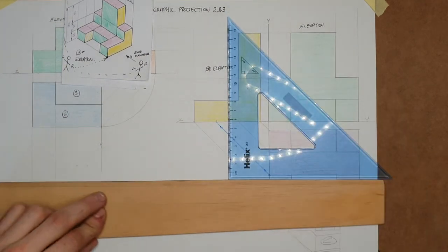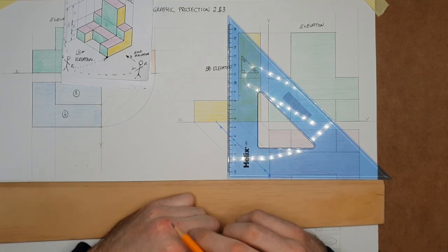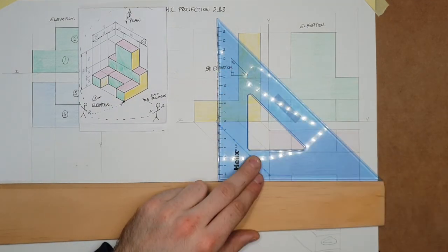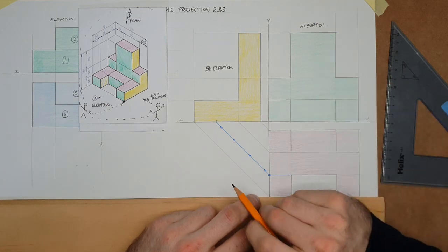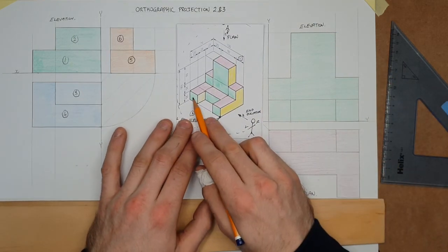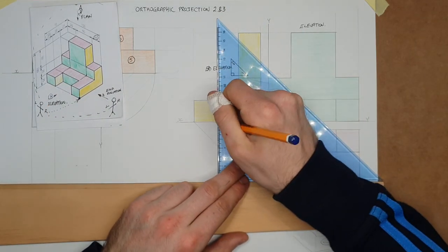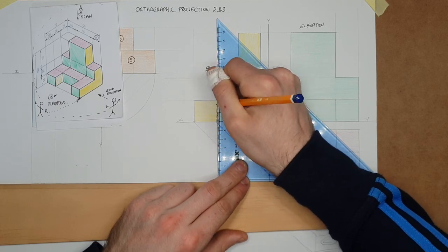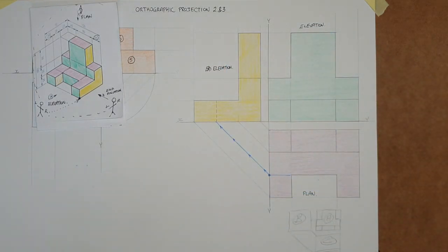The very final thing in this drawing is how do we represent a hidden detail. It's called hidden detail. There has to be a difference. I can't just draw a full solid line, because there has to be a difference between what's happening here, which is a full solid line. That full solid line shows that this surface stops and this surface starts. What we do this time is we do a hidden line.